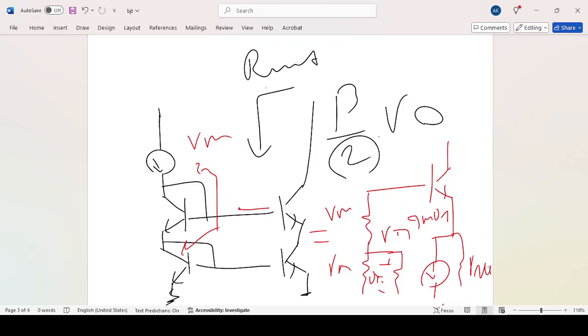The reason that you have beta over 2 here is that you have this small signal current source here that adds a current at the output. We know that when we have more current, we have less R out. So the reason is that, for example, in CMOS we do not have that. In CMOS this does not exist, and what we have here is R out only. Or in the other configuration that I showed you, if I delete this,